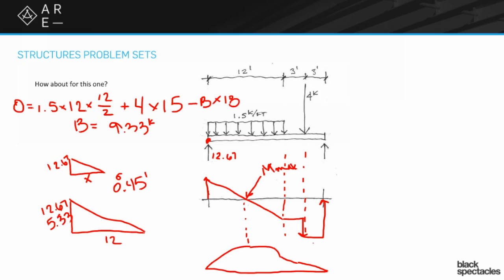And once again, just find the system that you feel comfortable with for how to think about these things. But if you think of it as the value of the shear diagram telling you what's going on in the moment diagram, as that sloping line goes, the value is dropping at every point, and you can see that the curve's slope is changing and becoming closer and closer to zero until it gets to that maximum point.